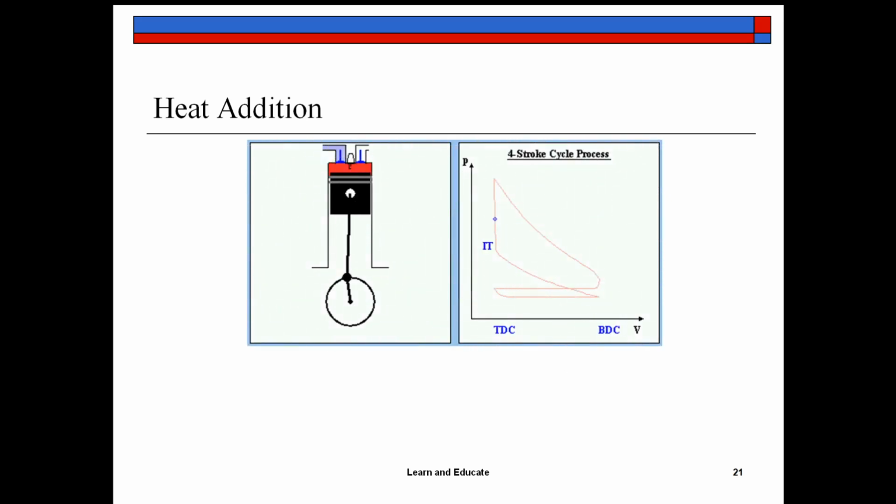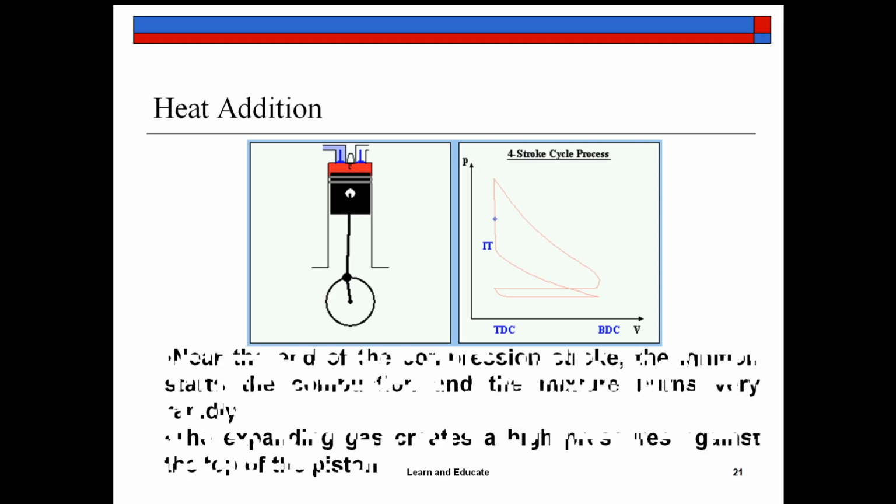Then at the end of compression stroke, heat is added. This is not a stroke, this is a process. Okay, this is not a stroke. Heat addition is taking place in the form of a spark from the spark plug. At the end of compression stroke, the piston remains in the top dead center position.